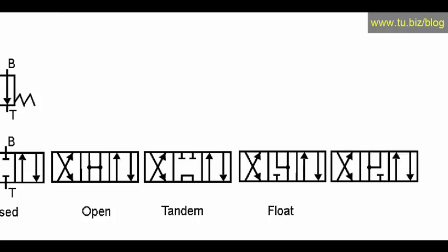We go to the following valve, and we have a regenerative circuit in which the pressure line is connected to port A and port B, and the tank line is closed. So those are some of the most popular options that we have for a three-position valve with the different centers.